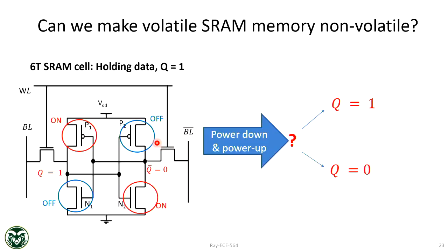One research approach we use is X-ray, because if you turn it on and put it under X-ray, then X-ray will deposit a lot of charge. Whichever transistor is on will be affected by X-rays. Whichever transistor is off will not. So you change the threshold voltage through X-rays.